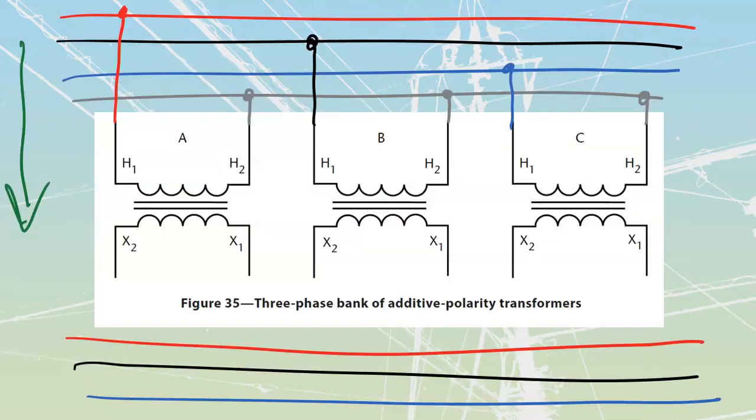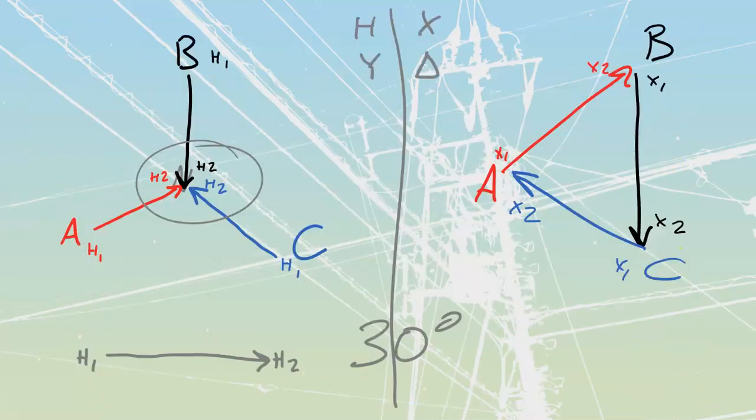The other thing that I want to point out is we are not going to put a ground onto this one because this is an existing system. It should have been grounded on the original install. We're not going to install duplicate grounds. We're not allowed to do that under Canadian electrical code. Because we're tapping off of it, we don't have to worry about putting a ground onto it because the system is already grounded. We would only have to ground any new systems that we create. And if we take a look, the system we're creating is not going to require a ground.